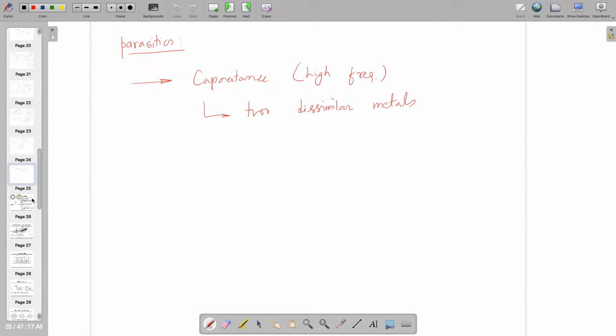So now, okay, we can complete this one also. We can see resistances also. They are available at any frequency, and it needs to have the path. So if I am drawing a line from here to here, 1 and 2 are different nodes of a circuit. If they are connected by wire, the path will have resistance. That's known as the parasitic. And if you are dealing with 1 and 2 at high frequency, it not only has resistance, but it will also have capacitance.